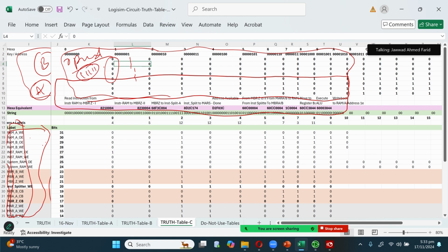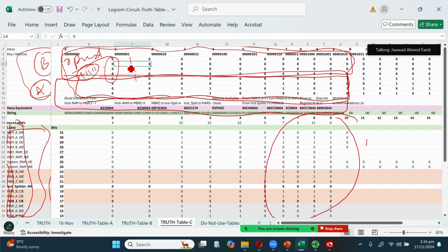What happens? Only this part will change. These clock cycles and the relative action that's happening with respect to those clock cycles will remain the same. Within some of these clock cycles, when you talk to the ALU and you tell the ALU add or subtract or mult, the relevant opcode would be different.